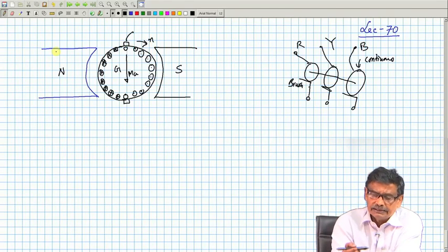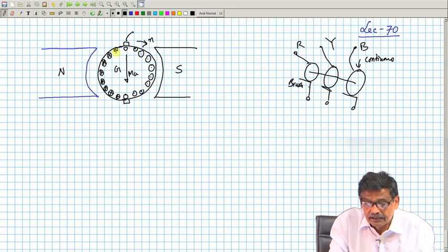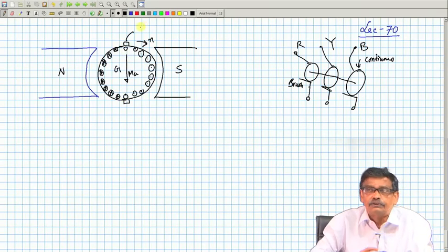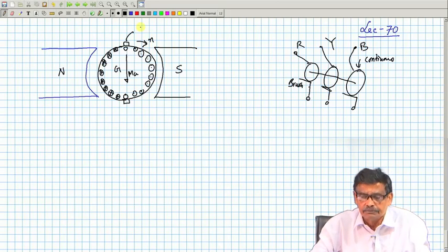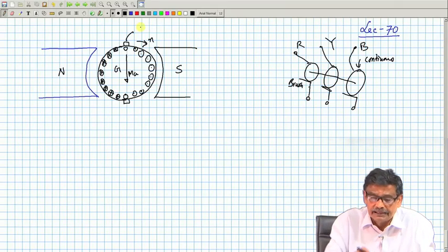So, that is why the rotor terminals in a DC machine are accessed by commutator segments and brushes, to make it DC. Also, when a particular coil comes to this position, then only these two ends get connected to the brushes, and different coils come at different times. That is why, in space, the position of the coil matters: whichever coil comes to that particular position in space gets connected through the brushes.